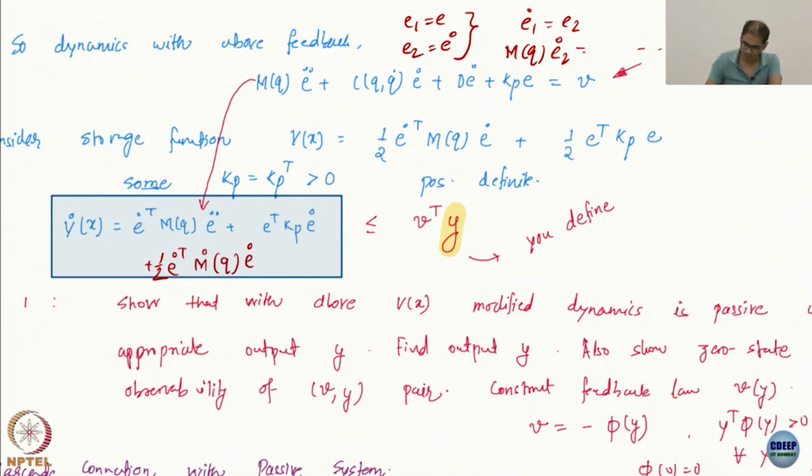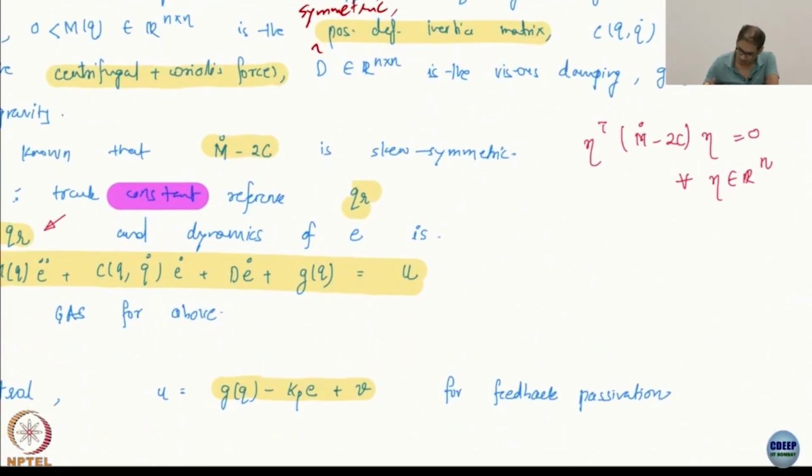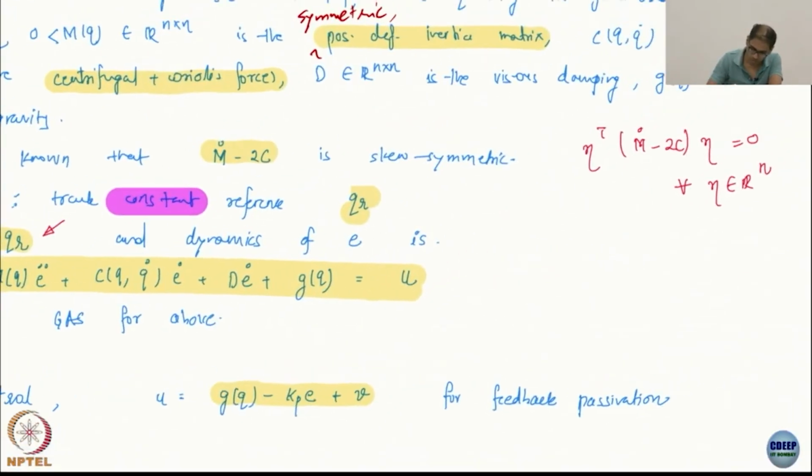All right, great. Now I am saying that this is a very standard construction for a Lyapunov candidate for the robotic system. If you get a robotic system, try this Lyapunov candidate. Why is this a nice candidate? First of all, M is symmetric positive definite for all Q. Therefore, this is already a nice positive term. Kp was chosen to be positive definite. Obviously, I don't know if I wrote this here. I really hope. Oh, disappointing.